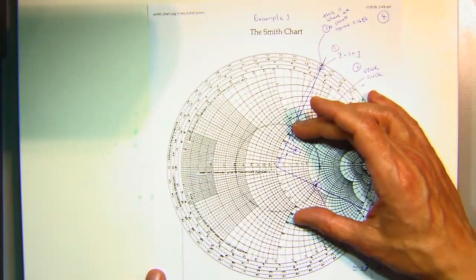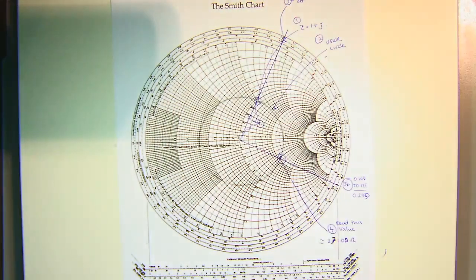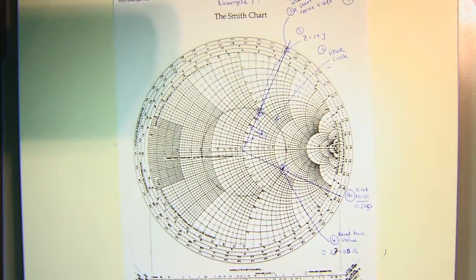The impedance actually changes. You can get loops which indicate resonances and things like that. And that's why on a vector network analyzer, S11, S21, and all the scattering parameters are plotted on a Smith chart. So you've all used the VNA?